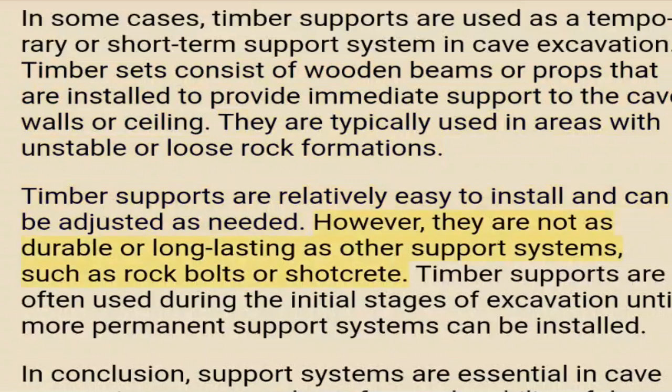However, they are not as durable or long-lasting as other support systems, such as rock bolts or shotcrete. Timber supports are often used during the initial stages of excavation until more permanent support systems can be installed.